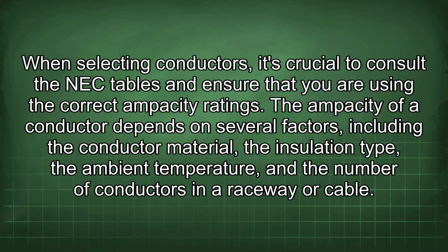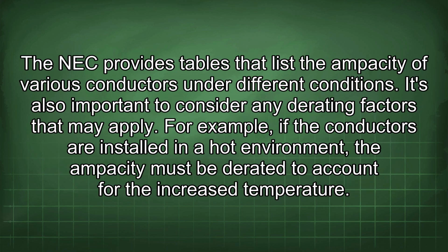When selecting conductors, it's crucial to consult the NEC tables and ensure that you are using the correct ampacity ratings. The ampacity of a conductor depends on several factors, including the conductor material, the insulation type, the ambient temperature, and the number of conductors in a raceway or cable. The NEC provides tables that list the ampacity of various conductors under different conditions. It's also important to consider any derating factors that may apply.